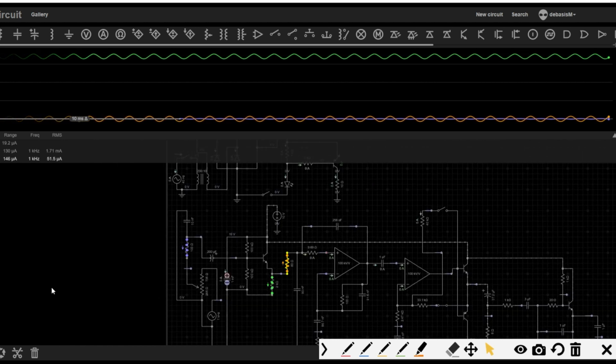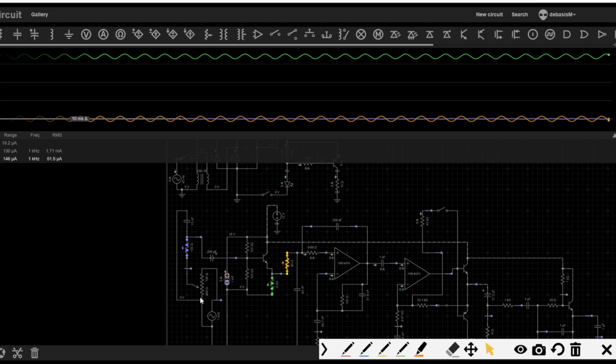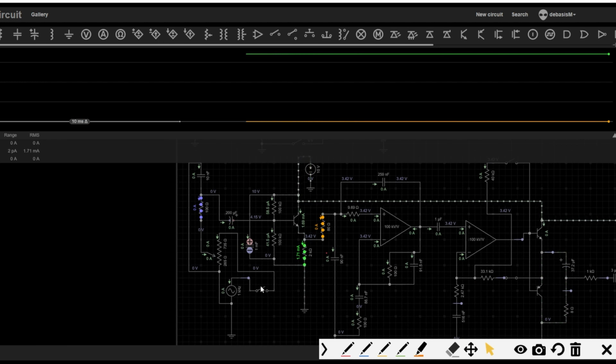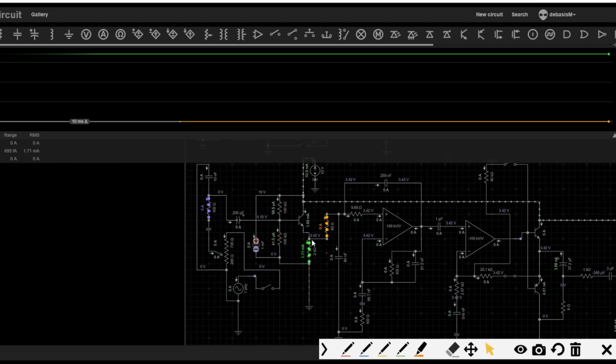Let's say, okay, let me open this audio signal supply. Even in that case there will be a current flow through this transistor. Let me show you. To demonstrate that there is no audio signal, I have attached a switch here in the audio signal loop. So if you see that this audio signal is not getting supplied, even in that case, that transistor is passing some amount of current to the ground.